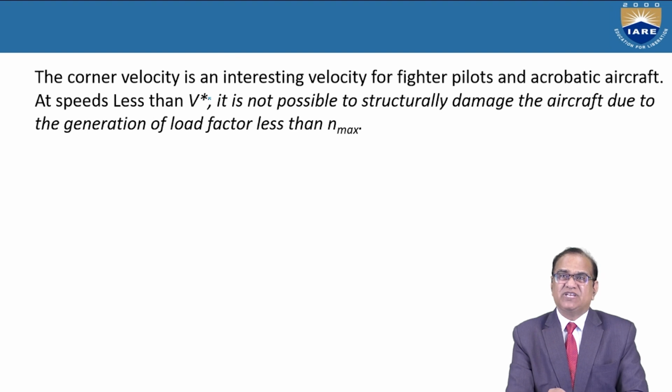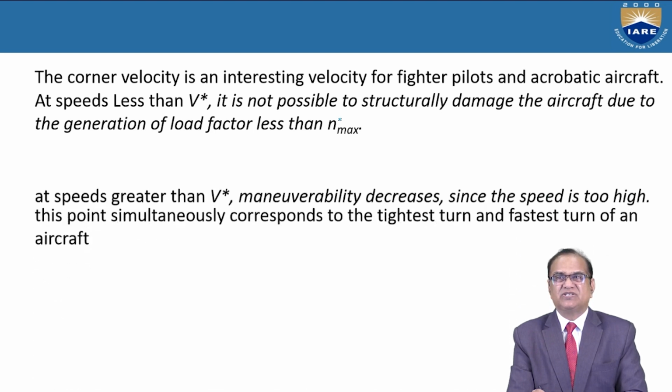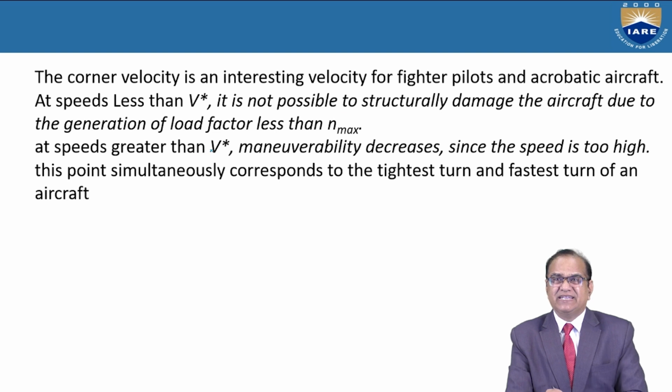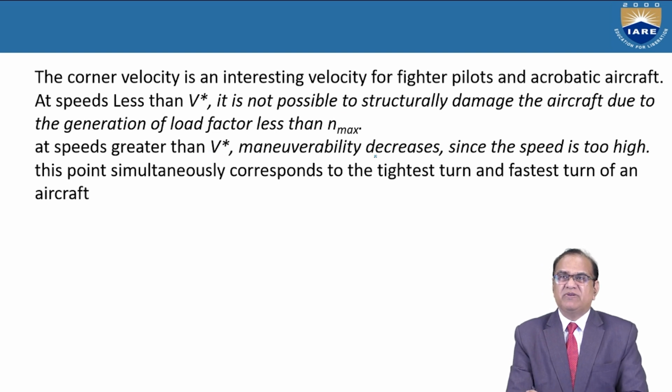At a speed less than V star, it is not possible to structurally damage the aircraft due to the generation of load factor greater than Nmax. So if you are flying less than this, your aircraft will not be damaged. At a speed greater than V star, maneuverability decreases, since the speed is too high. This point simultaneously corresponds to the tightest turn and fastest turn of an aircraft.